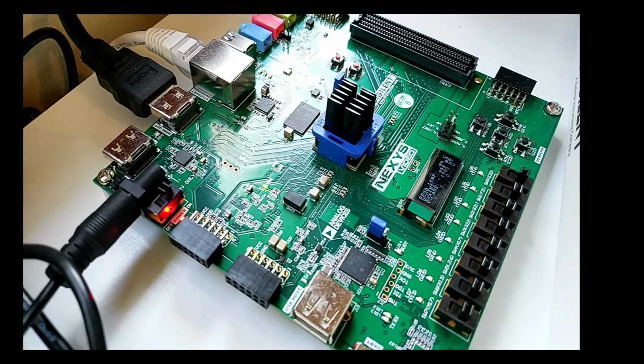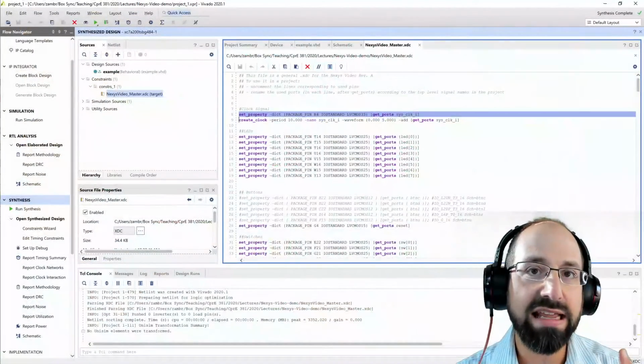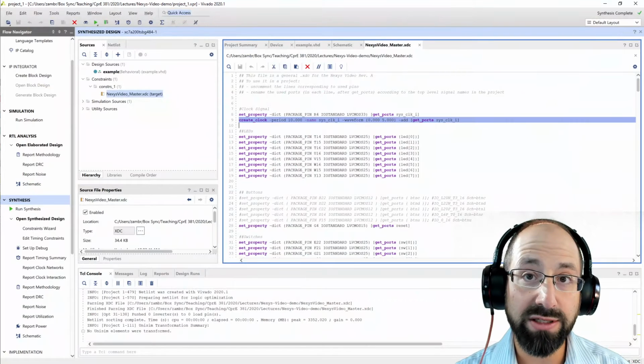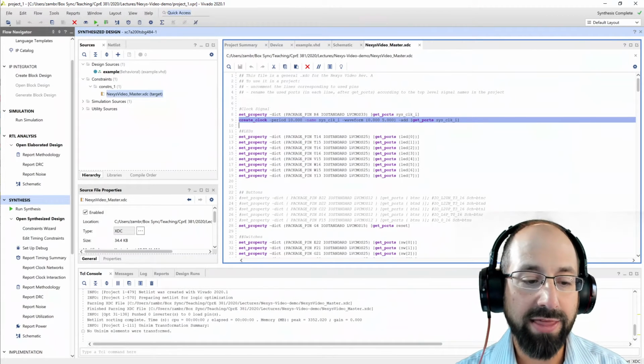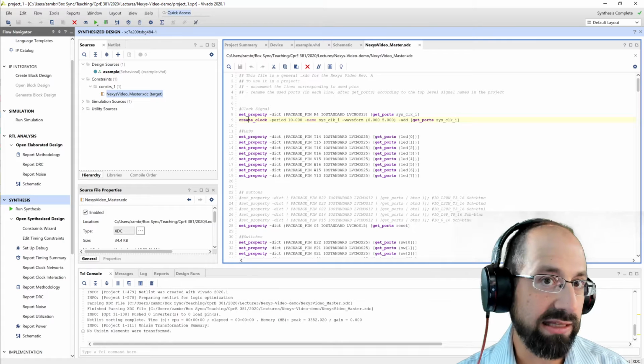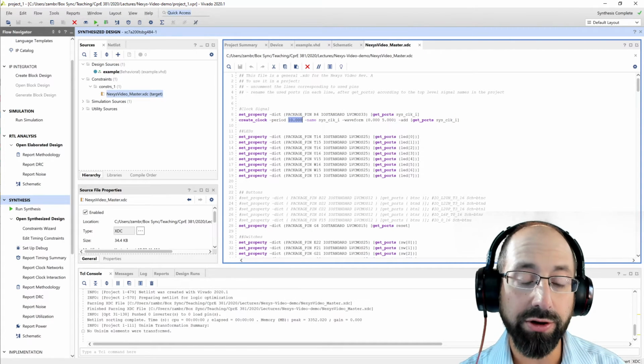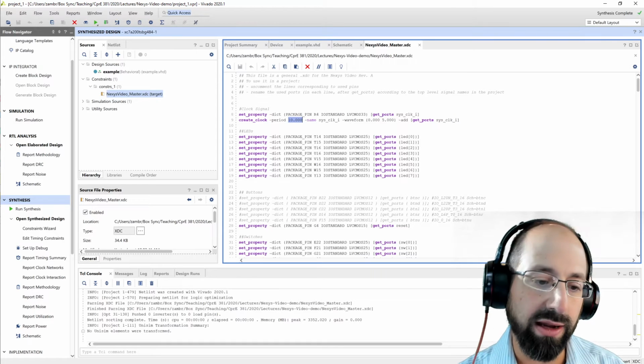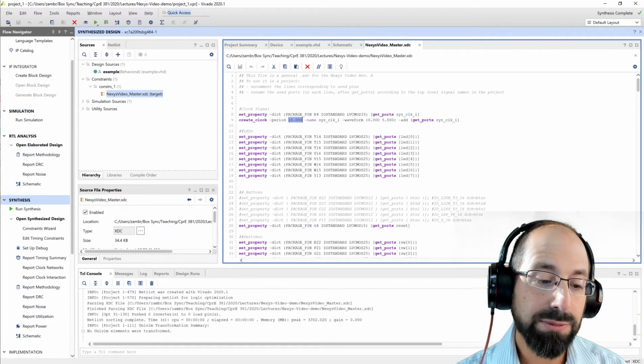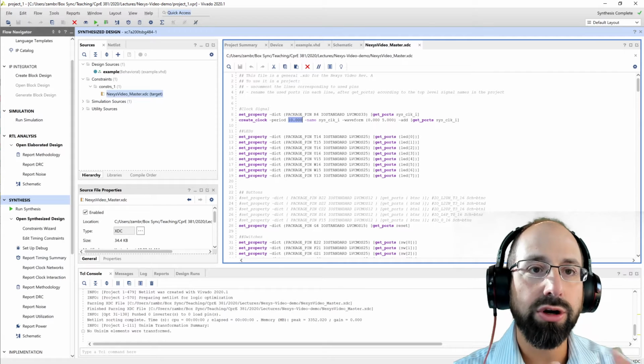We can do things on our FPGA to generate additional clocks, but as we analyze that input clock, we also have to be told and we also have to specify that it is a clock. And not only is it a clock that's at that location, it's also a 100 megahertz clock. So the clock period is 10 nanoseconds that we're specifying there. And that has pretty big implications, right? We talk about the critical path, and